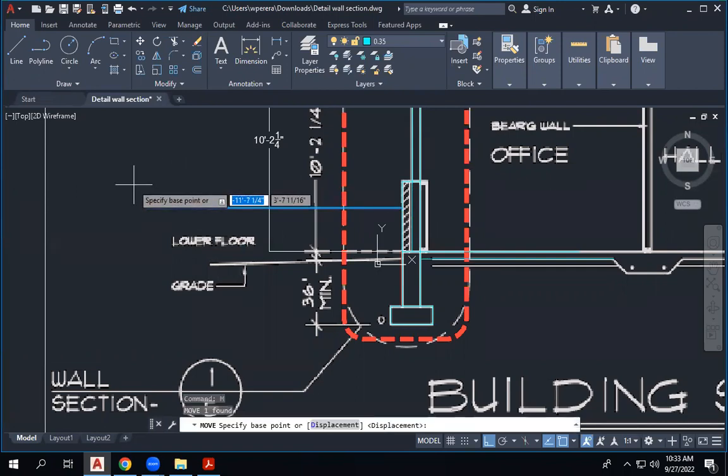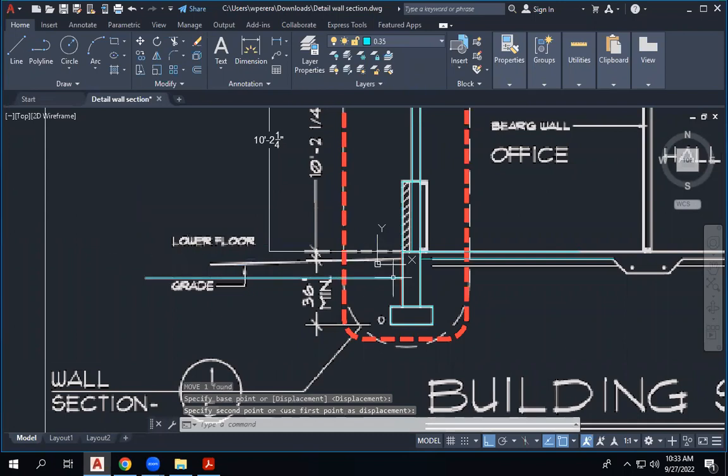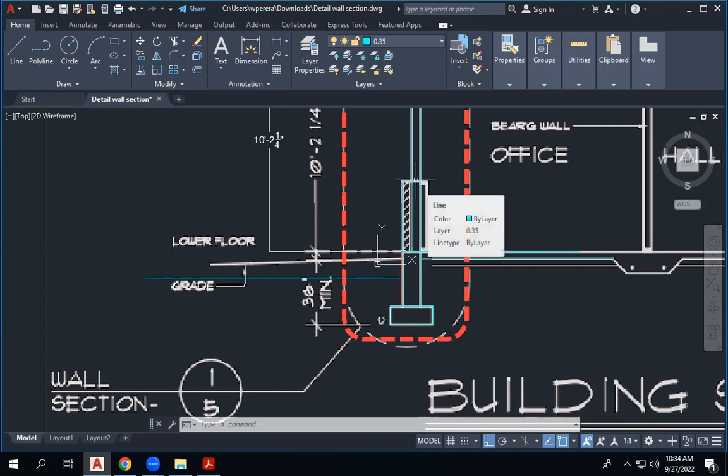So if it's like this, you can either stop your foundation here and have your wall from this point onwards, or you can have the foundation right up to the slab level and have the thinner wall here. Most of the buildings you see outside have a step up. The foundation goes right up to the top of the slab. From that point onwards, this will work as the wall.